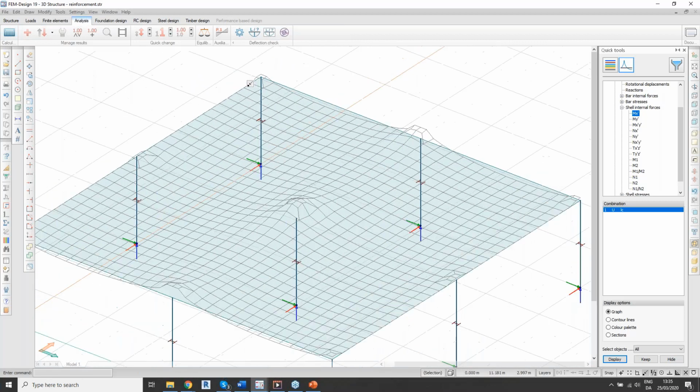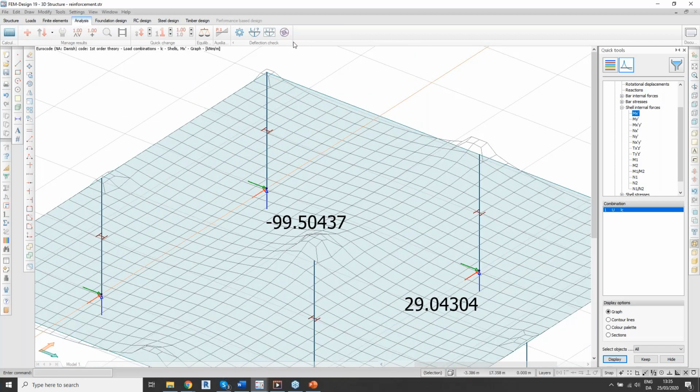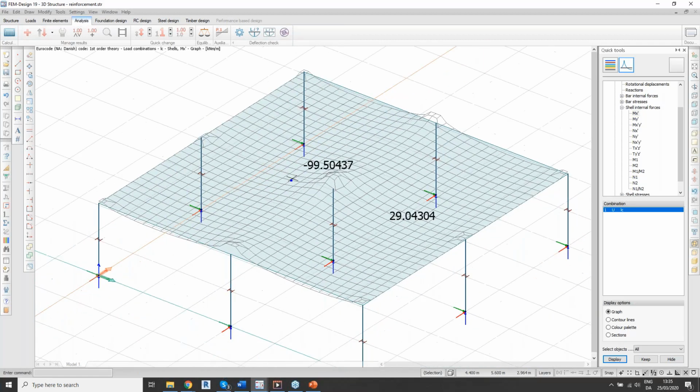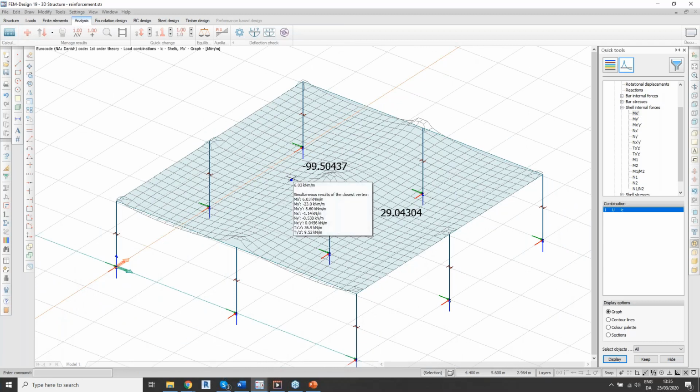It's actually pretty good. It's the difference between constant shape and higher order shape. Again, it's up to you how you use it. I use higher order shape when calculating cracked section analysis. I use constant shape function when simply calculating the bending moment and making a check for that. You have both options available.